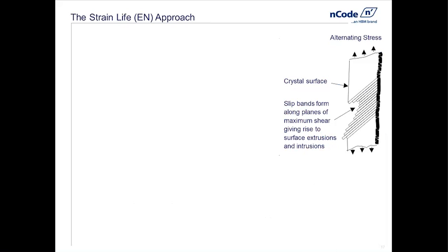And there are defects, there are molecules missing, or there are these things called dislocations, and those serve to limit strength, unfortunately. Microscopically, materials don't fail because of breaking chemical bonds in tension, but rather by sliding them past each other, by shearing.